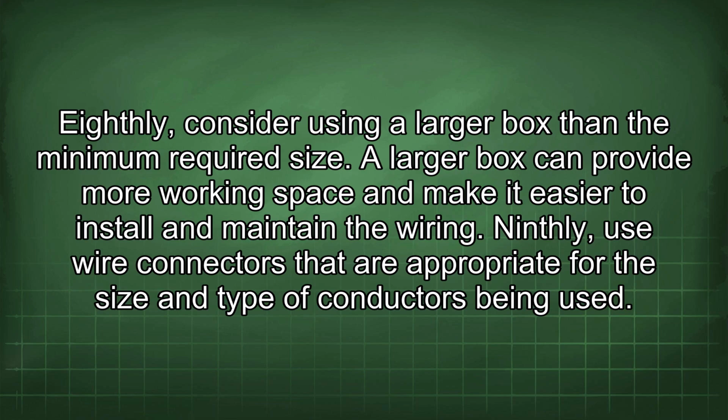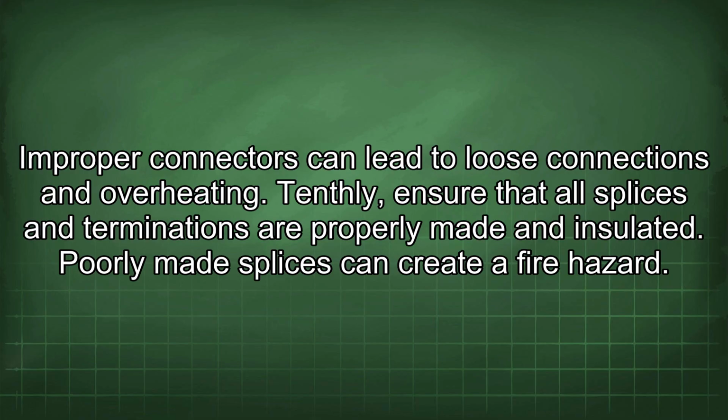Ninthly, use wire connectors that are appropriate for the size and type of conductors being used. Improper connectors can lead to loose connections and overheating. Tenthly, ensure that all splices and terminations are properly made and insulated. Poorly made splices can create a fire hazard.